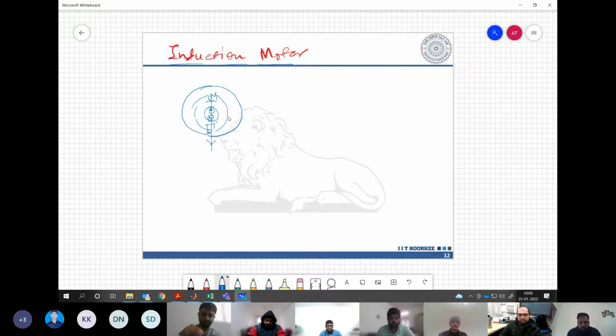So the force is coming over here, or actually the opposite direction, the force will come in this direction, right? Basically not torque, I should write force. It becomes torque when it is on the rotating body. Now when the force is applied, it rotates, and then this positive direction of current comes near the south pole. Then the force will be reversed because the direction of current is reversed.